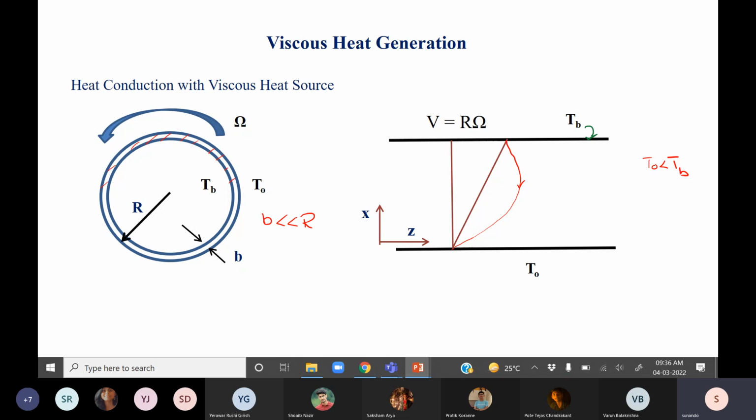So in terms of developmental logic, a favorable pressure gradient plus Couette flow is similar in concept to two plates having different temperatures, where one is moving. However, there is an additional source term present in the intervening liquid between 1 and 2. Agreed? So that's the corollary between heat and momentum transfer, which you could see.